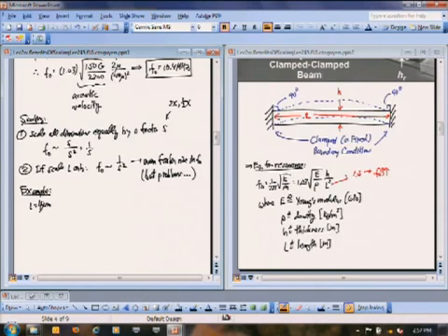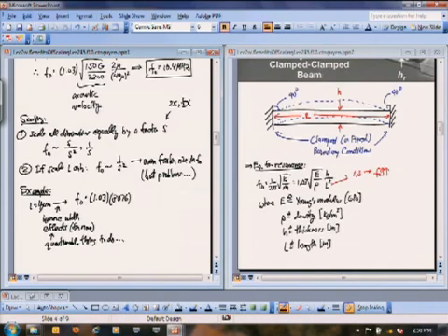Okay? But if we do this, we can then just plug into our frequency equation. This becomes 1.03 times this acoustic velocity, which I'll now give as 8,076 meters per second, times thickness, 2 microns, divided by now 4 microns in length.